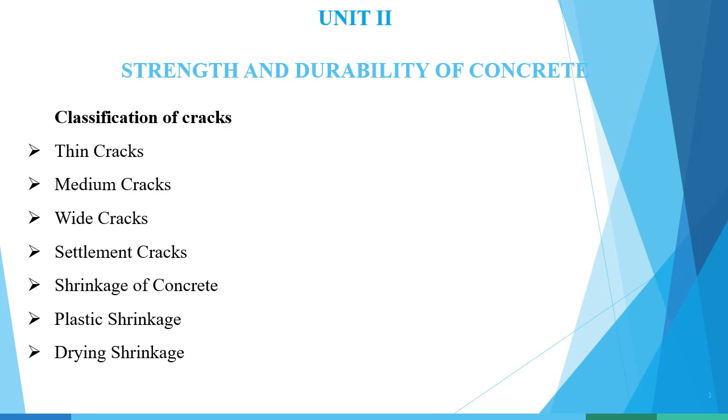When we discuss the shrinkage of concrete, the following aspects of shrinkage are required to be considered. The next one, plastic shrinkage. Water from fresh concrete can be lost by evaporation, by absorption by subgrade and formwork, and in the hydration process. When the loss of water from the surface of concrete is faster than the migration of water from the interior to the surface, the surface dries up. This creates a moisture gradient which results in surface cracking while the concrete is still in plastic condition.